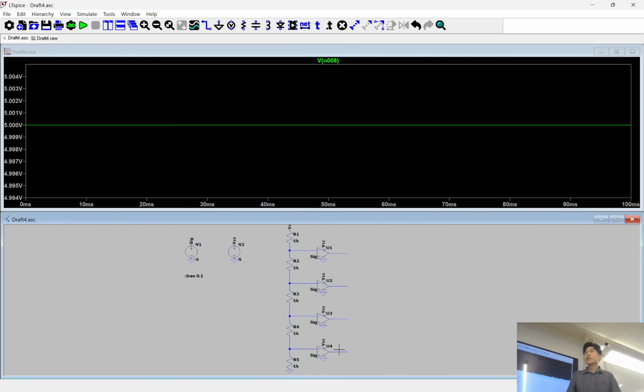So the idea here is we're taking some analog value as our signal, comparing it to a bunch of fixed values, and depending on that result, I get essentially zeros and ones as my output, right? Because 0 is low, 1 is high. That's one way in which we can convert analog into some digital value.